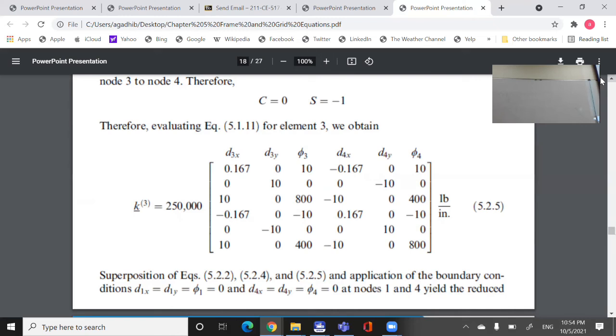Put in the displacements we got. Do you know the forces? What are the forces at node 1? I think shear, axial force, and moment. These are the 6: 1, 2, 3, 4, 5, 6. Now, you have to find K local, which is 6 by 6. You multiply it by the D. Yes. And that will give you the forces.